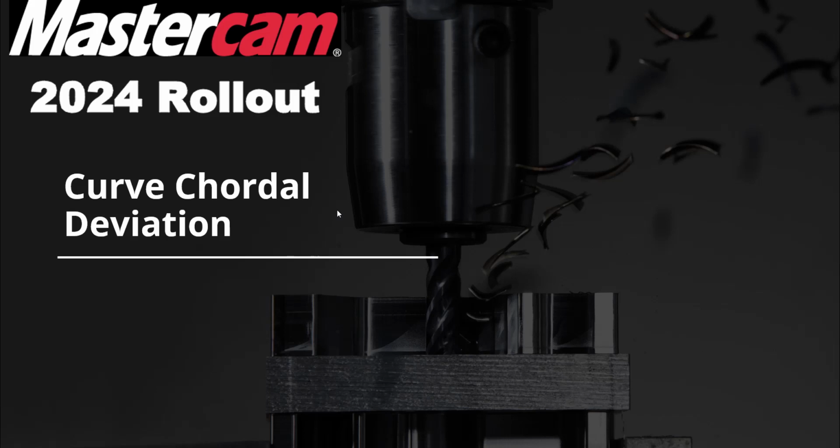Several years ago now it was added again, and if you're not familiar with this toolpath, when I used to train it, I would kind of ask people if they use Flowline. A lot of people use Flowline. Flowline has some pretty common weaknesses. If you have a lot of faces, the UV directions could be mismatched.